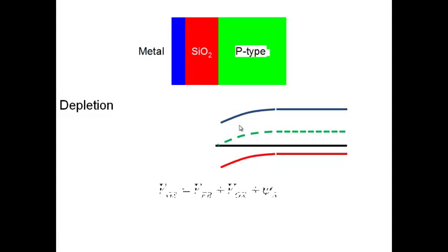Well, look at this. Does it make sense, this diagram? First of all, I create a flat band. How much voltage do I have to apply? VGS equal to V flat band. Then on top of flat band, I have to apply extra voltage to bend the bands down. Right? Extra voltage I have to apply. That extra voltage, where is it going to drop? VGS, you're applying the voltage between here and here. That extra voltage, some of it is going to drop here and some of it is going to drop here. And that's why any voltage that you apply more than the flat band creates band bending.